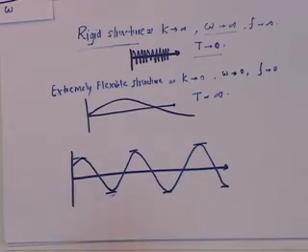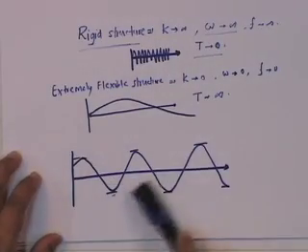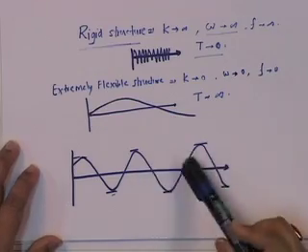Okay. This will remain for all times. In other words, if we go back to what I am looking at, it is vibrating in this way, it will keep vibrating. Once I give it an initial displacement and it starts vibrating, it will keep vibrating. That is what this equation says, and it keeps going on and on and on. Okay. So, once I vibrate it, it will keep vibrating forever. Now, in the real world, this does not happen, right, because you must have vibrated systems and you have seen that they start vibrating and then they slowly decay and they slowly come back.